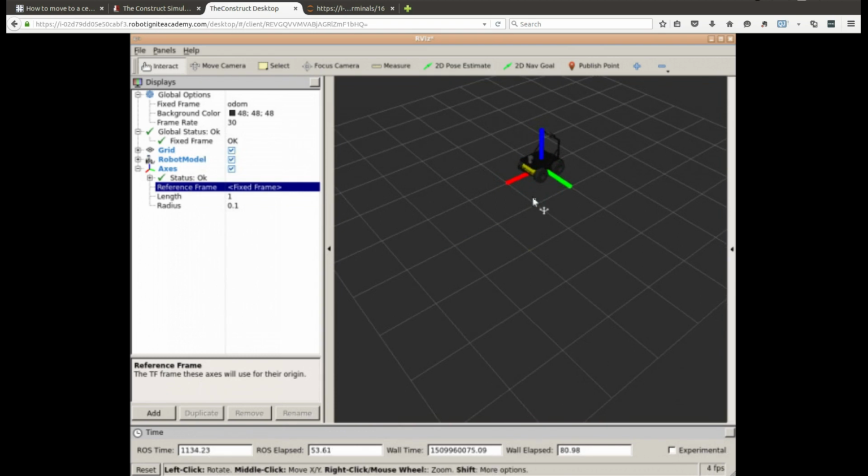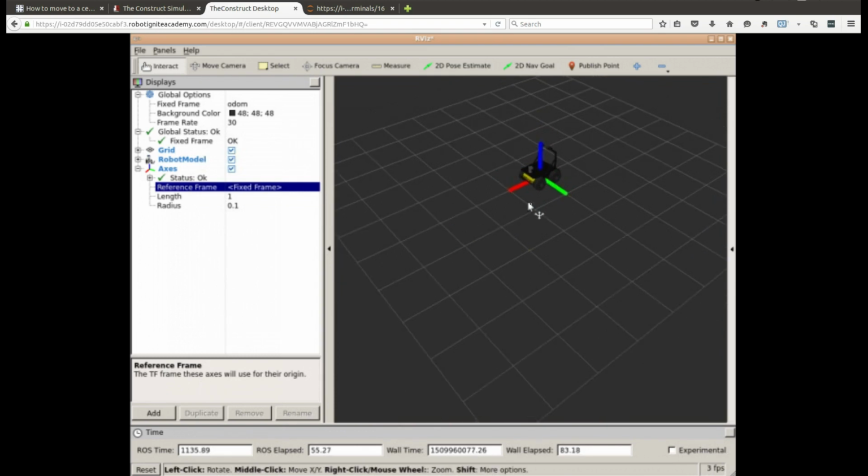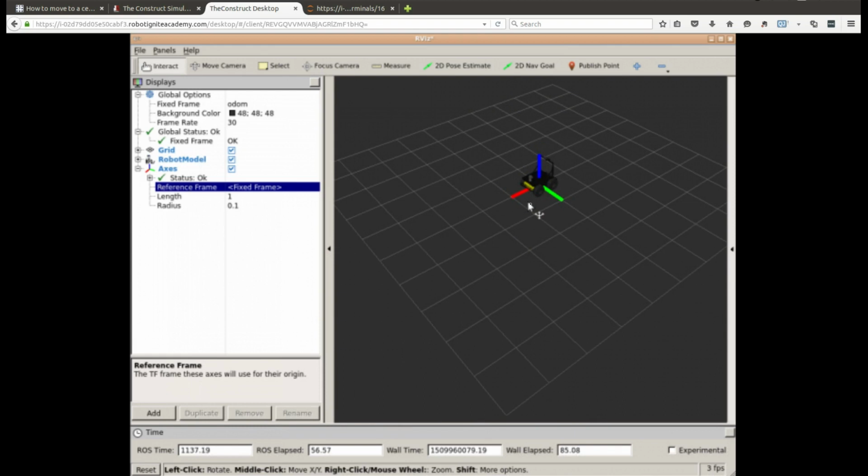So now we are going to send this program, and then in theory the robot has to move to the position, sorry, to the position 5, 5. That means 1, 2, 3, 4, 5. So it has to go towards this direction. Because the robot is not facing the goal, because it's facing this direction, then first it will have to turn and then come in this direction.